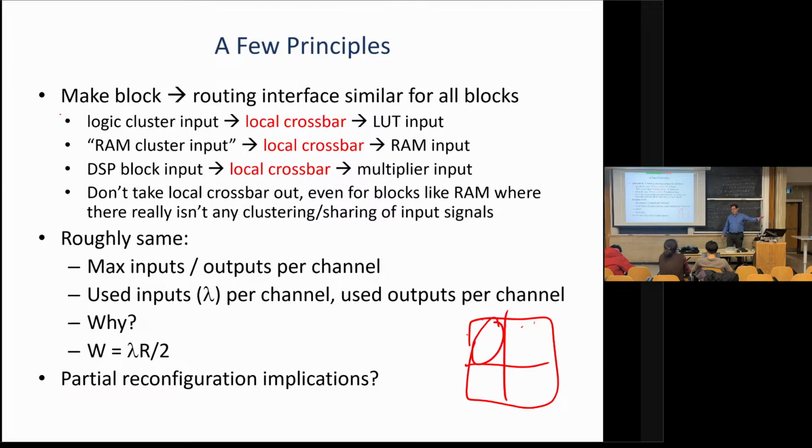Like the person who decided they don't want to pay for all this. Nobody cares that their stuff's being reconfigured and it's not available for 10 milliseconds. They do care that none of the other ones were disturbed. So that was the key use case that we saw for partial reconfiguration: very disciplined, slowly changing, a system that had many communication protocols that it would change between quite slowly.